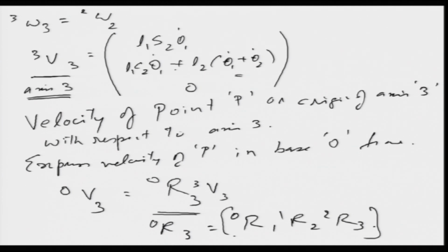So, what we need to know in dynamics is essentially what are the forces, and by forces I mean torques or moments, required to cause motion, and the equation of motion of a manipulator. Okay. So, dynamics will give me both of these, because that is required from the control point of view. When we are controlling the manipulator, we have a controller and the controller needs to know how much torque to give to the motor, and that would depend on the forces, and that would depend on the kind of motion that is desired at the end effector. Okay. So, let us look at dynamics now. So far we have been looking at kinematics. Now, let us look at dynamics.